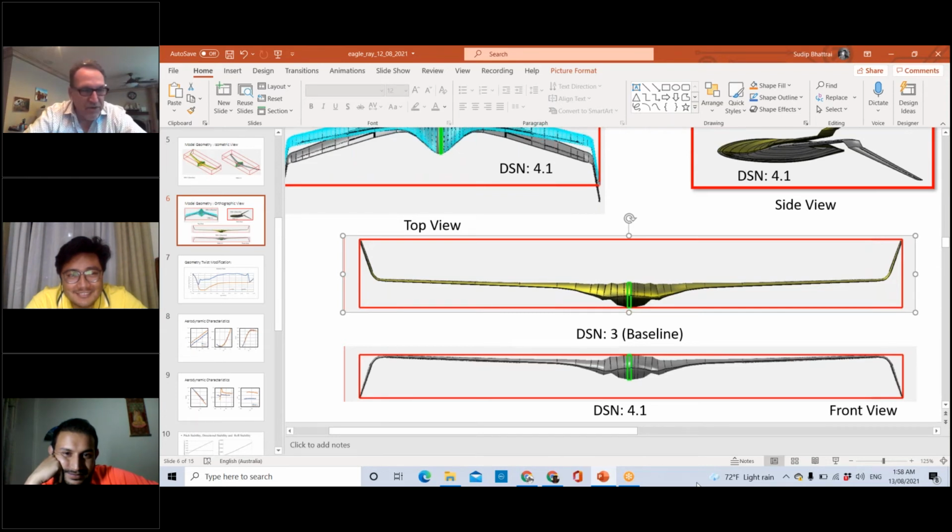Once you shear the airfoils and get it kind of close, a trick we do all the time is we'll take, let's say, the centerline airfoil and we'll go out past that first airfoil to between the first and the second airfoil, and I'll have my loft guy take a cut there, and then I'll have him take a cut between the next. Sometimes if we take cuts between the airfoil defining stations and throw away the original airfoils, you'll almost always start smoothing the surface. And yet, in a strange way, you're preserving the average effect.